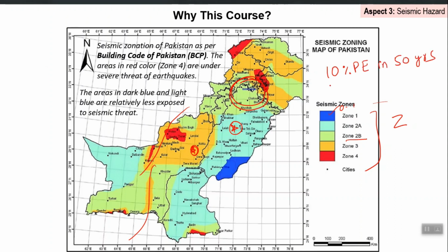right? So if I pick the PGA value from this particular location, it may be, let's say, 0.25 g. Now this 0.25 g is following this definition, 10% probability of exceedance in 50 years. So whenever you make a hazard map, you follow a particular definition, and at that definition you report PGA values or any other hazard values, right?